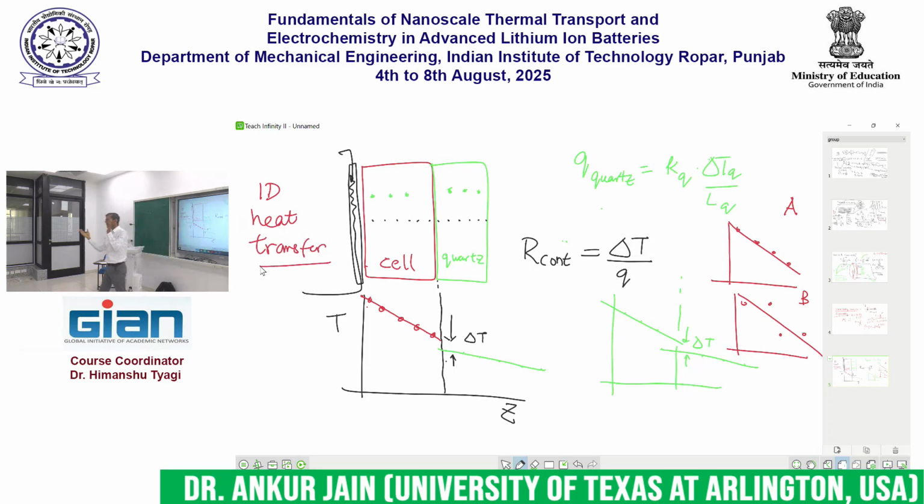And when I have one-dimensional heat transfer, the temperature distribution is a straight line, theoretically speaking, right? If my measurement also gives me a straight line with very good variance, then that gives me confidence in my measurements. If on the other hand I find that my data looks like this, then what this is telling me is that heat is entering the body but it is leaking away somewhere along the way. It's not all going in a straight line.